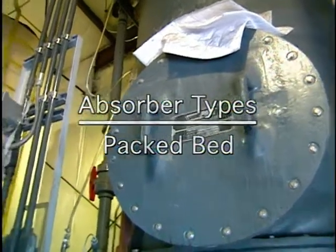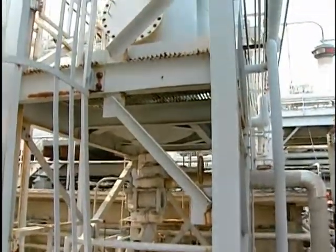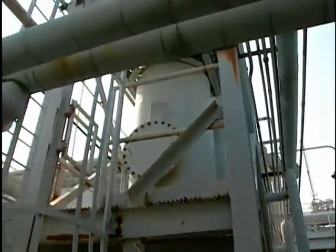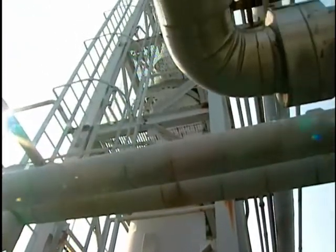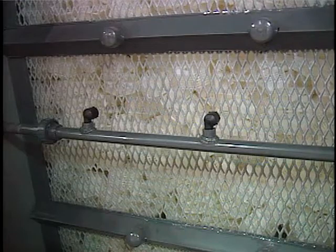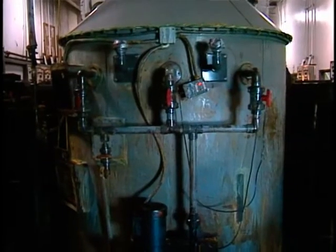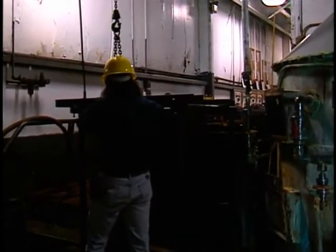Packed bed absorbers are the most common design used for gas collection. Packed columns spread the liquid over packing material in order to provide a large surface area for gas-liquid contact. There are many designs for the packing materials, but they all have large surface area while maintaining open areas for the gas flow. Although they are usually made of plastic, metal and ceramic packings are available when plastic cannot be used. Like spray towers, packed beds are classified according to the relative direction of the gas and liquid flows.